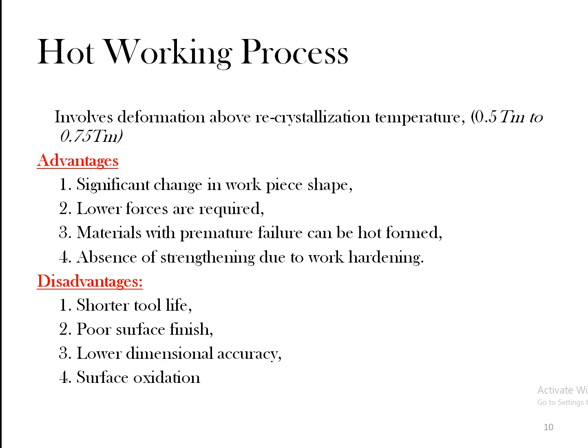Aerospace industry, since it is to be transported to outer space, all we need is a lightweight material, but the strength should not be compromised. Correct. So one of the best materials for this is actually aluminum and high strength steel: aluminum alloys and high strength steel alloys. But the problem with these two materials is that they cannot be formed easily, because since it is happening at low velocity, the tendency to form cracks is more for these materials. Now, how can we solve this problem, right?